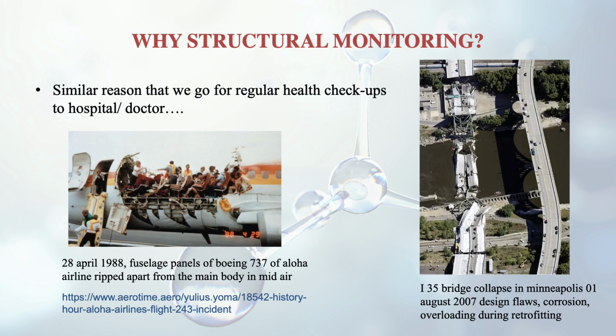The underlying cause of this accident was later found to be the appearance of multi-site cracks in the skin joints. These led to the unzipping of large portions of the fuselage. They were undetected during the routine pre-flight inspections.